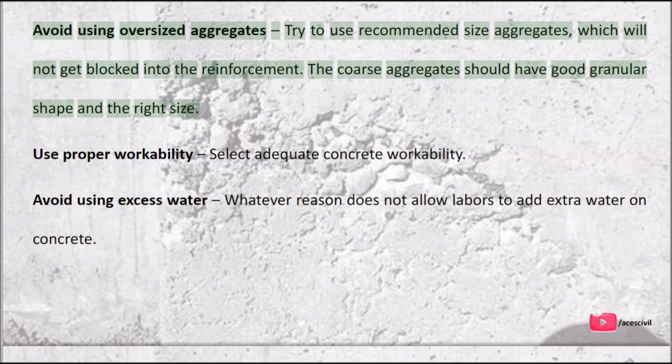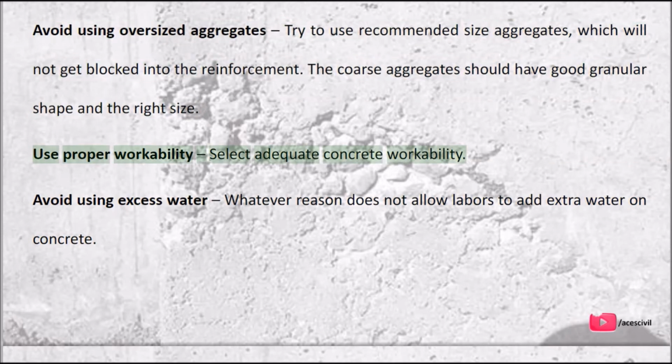Avoid using oversized aggregates. Try to use recommended size aggregates, which will not get blocked in the reinforcement. The coarse aggregates should have a good granular shape and the right size. Use proper workability. Select adequate concrete workability. Avoid using excess water. Whatever the reason, do not allow laborers to add extra water to the concrete.